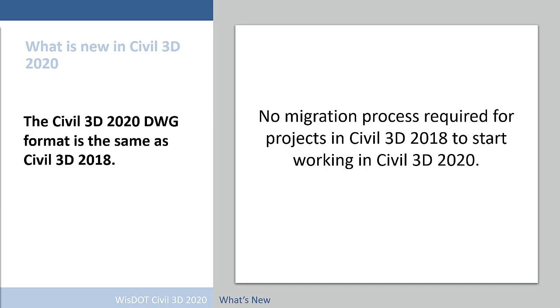There is no migration required for Civil 3D projects that are currently in the 2018 version. It is merely switching Civil 3D versions. Simply let everyone that is working on the project know that the 2020 version is now going to be used, and then start opening drawings in Civil 3D 2020.